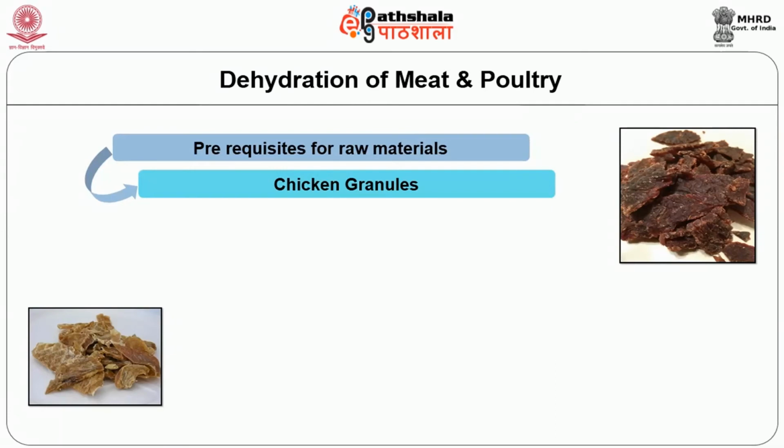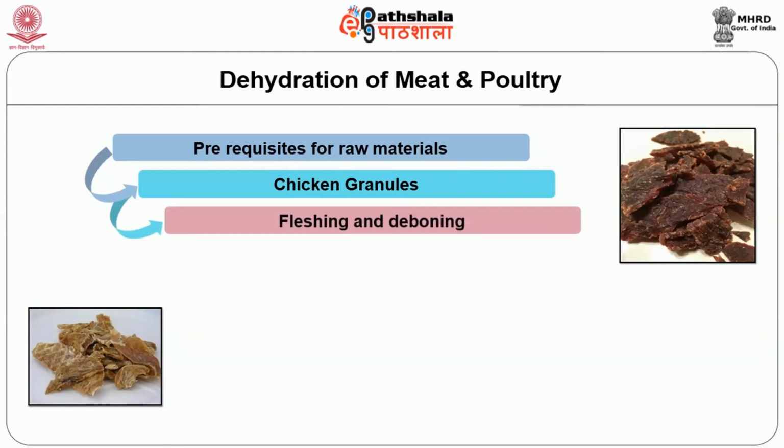The collected fat is used as a soup ingredient. The bouillon is also concentrated and added to processed flesh in the final stages. The fleshing and deboning operation is done on a deboning table, where the flesh and the bones are removed and filled into sterilizing trays. After meticulous examination for the presence of bones, the flesh is transferred to a slow-moving bladed steam-jacketed mixer, and the addition of recovered bouillon and salt is done for 15 minutes.